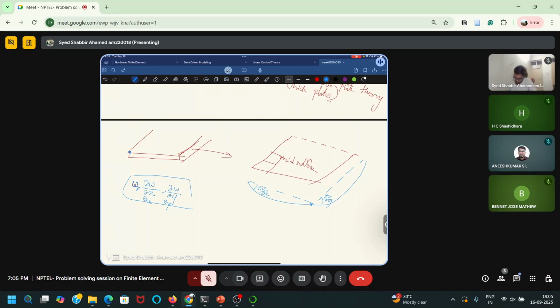If you want to learn how we get the equations of the plate, that is a very detailed process, and we have to follow the procedure, taking the assumptions of Kirchhoff plate theory, like assuming that a plane section will remain plane. Kirchhoff plate theory is the equivalent of Euler-Bernoulli beam theory, so both have the same assumptions.